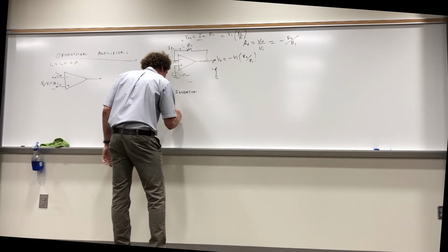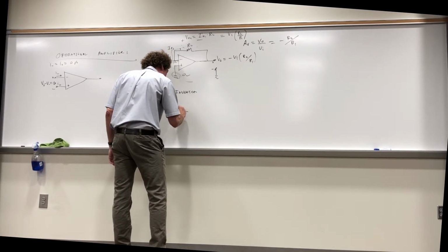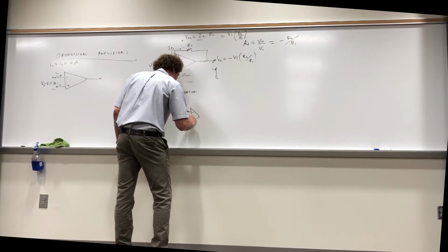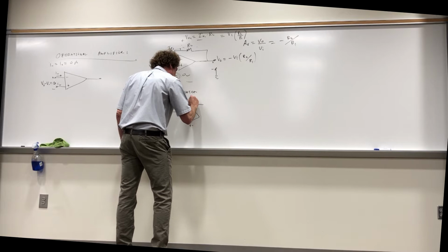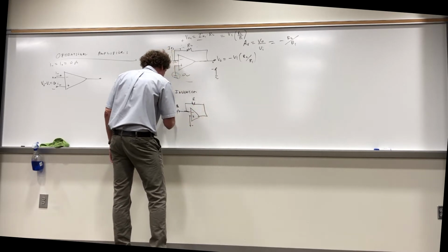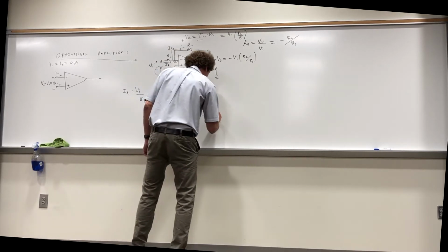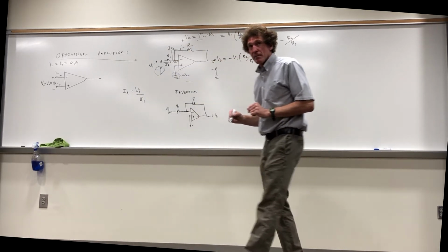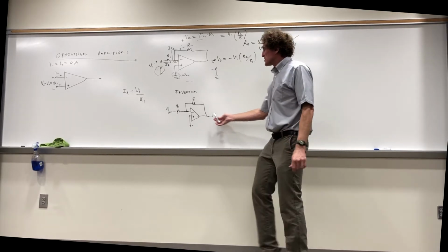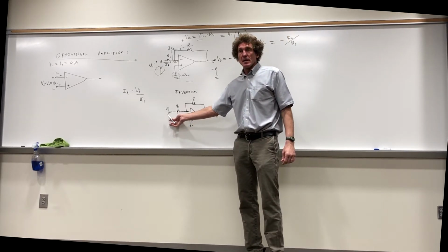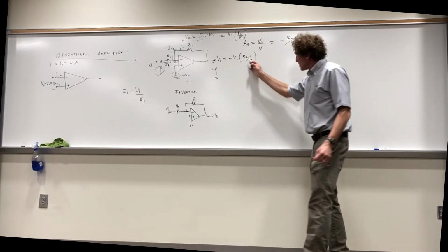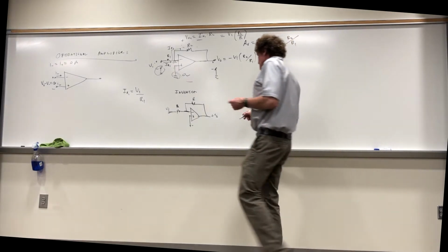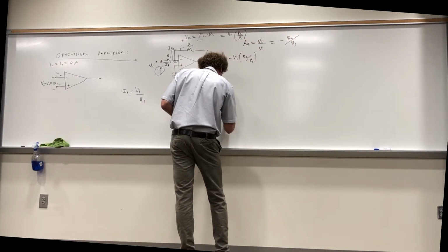and just have a resistor here of R coming to the op amp, negative, positive. Another resistor R here, same exact value. This is V in, this is V out, right? Now those two resistors are equal, right? Y'all see that? What is V out going to be? It's just going to be minus V in, isn't it? If the resistors are equal, then you basically get just minus V in as V out. So V out for this one is minus V in.